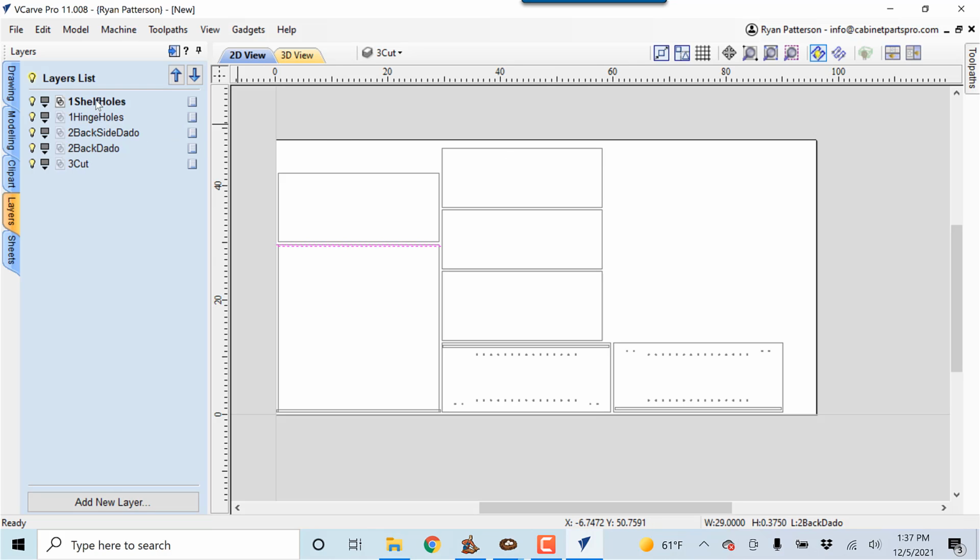So now that we have an understanding of what we're going to be doing, the first two toolpaths we'll use a drilling method for. And we're going to go over to the toolpath template. So normally you would want to switch from the drawing side to the toolpath side. In this case, I want to have the layer tab open as I'm creating these toolpaths, just so we could get a flow and an understanding of what we're processing.